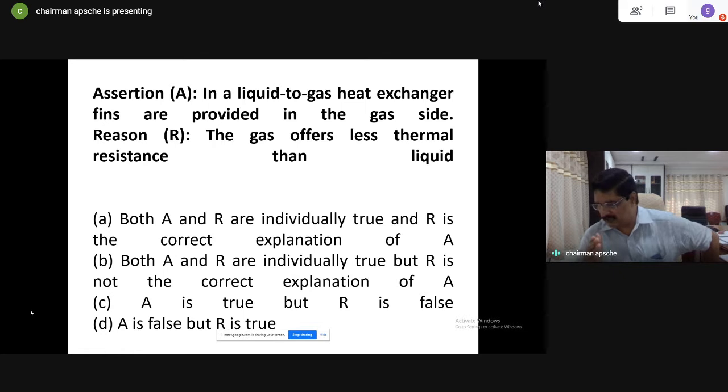Like I was slightly touching upon, when you have a plate on which the fluid is moving, the first layer of fluid initially comes to a no-slip condition, meaning the molecules get deposited on the plate straight away. And absolutely they don't move because of the heterogeneous friction or wall friction, whatever I said. So when the molecules are sitting pretty on the solid, the mode of heat transfer that happens, and therefore the convection heat transfer comes into play.